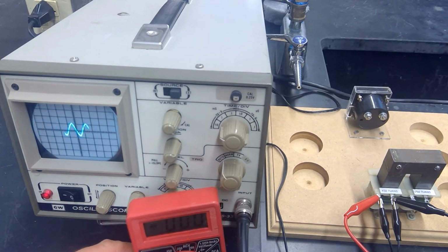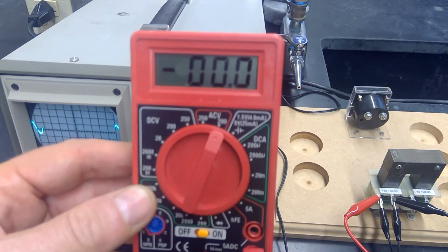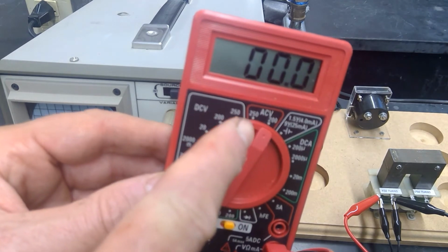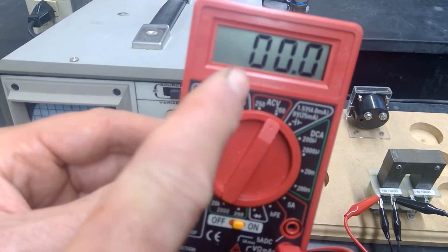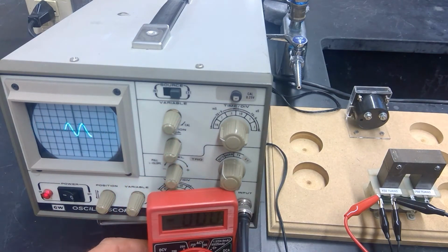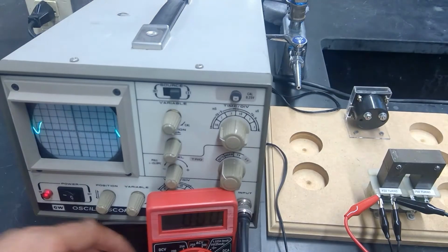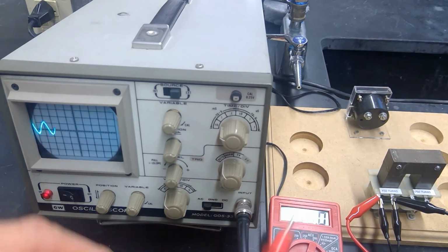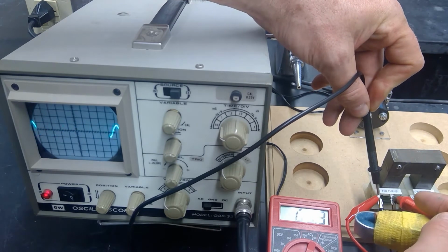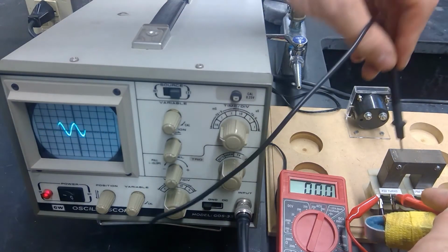Okay, so I'm going to put a little multimeter here that is set to AC. It's set to reading alternating current. Whenever you use one of these multimeters to measure voltage, make sure you know whether you're looking at DC or AC, and also try to set the appropriate voltage range. We're assuming that we're going to have less than 200 volts AC, and so I'm set for there. So I put the two leads of my multimeter across the primary, and we see pretty much 5.9 volts. Okay, try to get a little bit better there.